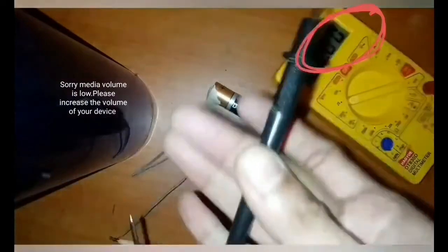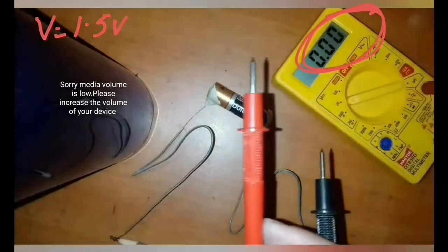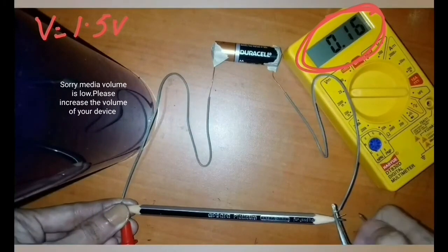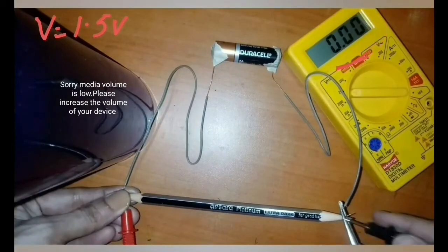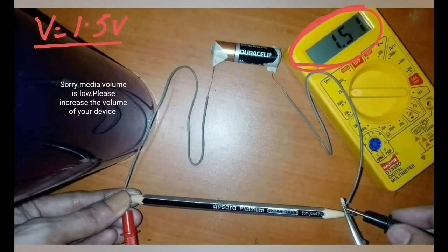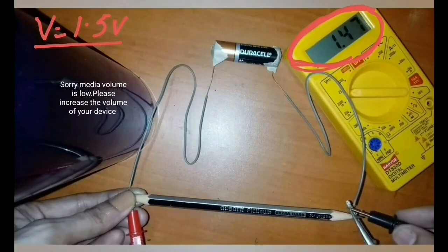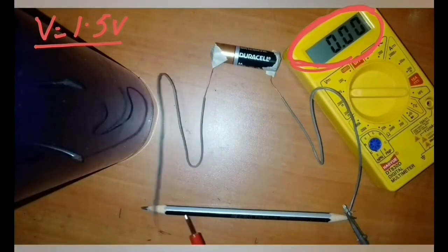This is the positive terminal, the red one, and this is the negative terminal of the multimeter. In order to find the potential difference, you have to keep the positive terminal on one end of the pencil and the negative terminal, that is the black terminal, on the other end, and just note down the multimeter reading. You can see it is around 1.5, 1.49, because we are using a cell of voltage 1.5. So almost 1.5 volt will be across the pencil. So we can note down that voltage as 1.5 volt.